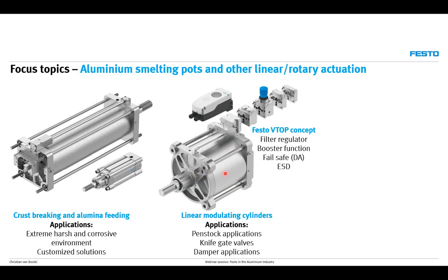Here we see the cylinder, which is configurable in terms of bore sizes, but also the length of the cylinder. And here you do not see, for example, the integration of the displacement encoder, because we integrated this into the cylinder. This signal is communicated with the positioner on this side, but where there's a big difference from the previous design till now is that the filter regulator, any type of booster functions, fail-safe functions, or even emergency shutdown applications are integrated in our V-top concept.